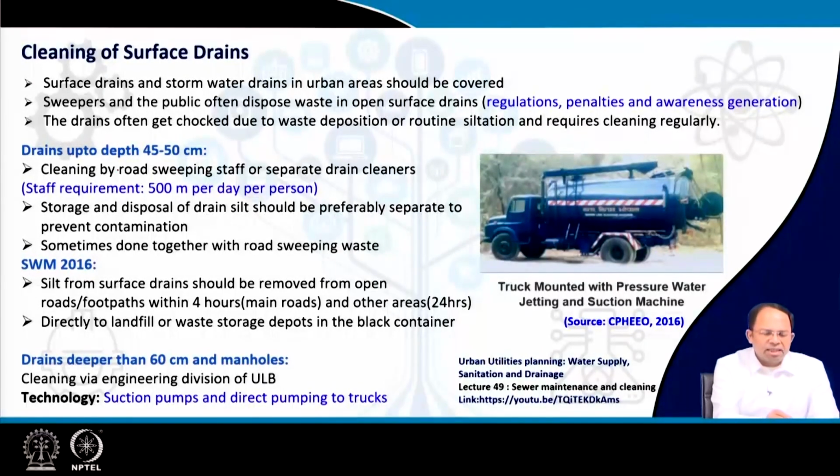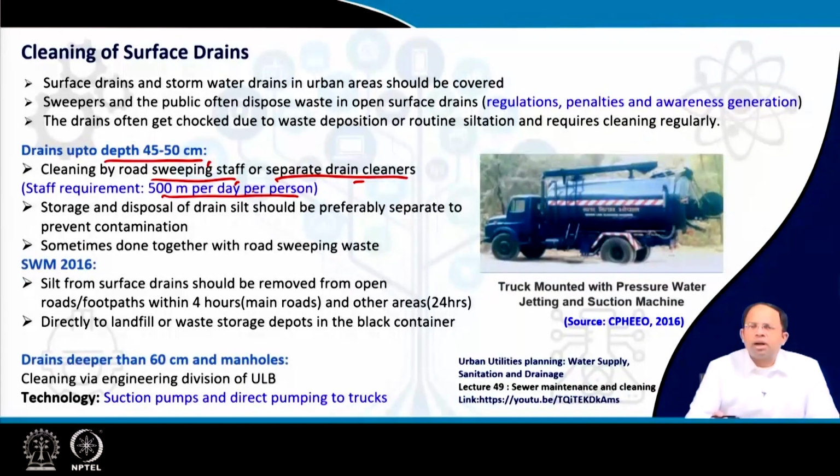So, drains up to a depth of 45 to 50 centimeters are cleaned by the road sweeping staff themselves, or we can have another group of staff in the same team, like drain cleaners, who can take care of this. And the staff requirement is similar, almost 500 meters per day per person. So, that's how much staff you require. Based on the kilometers of road, you can determine the staff for cleaning of drains, in addition to cleaning of streets.